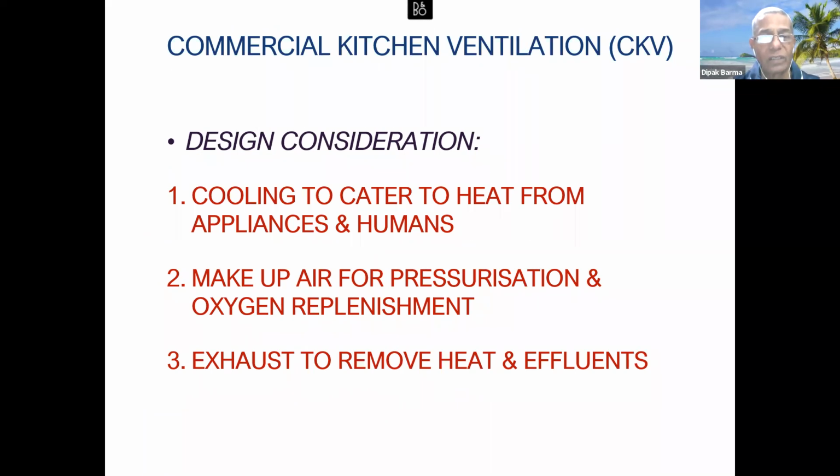Design consideration: one is cooling to cater to heat from appliances and humans, make up air for pressurization and oxygen replenishment, and exhaust to remove the heat and effluents.